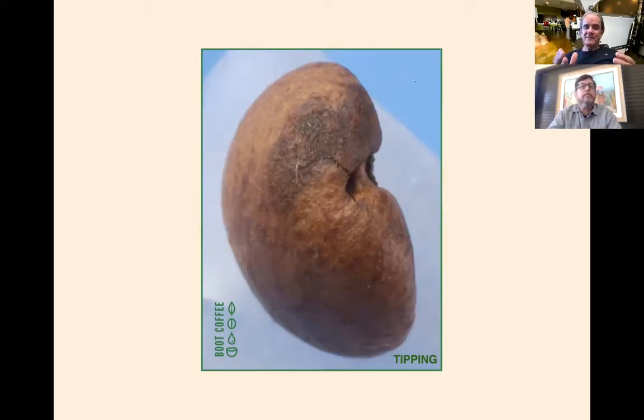Could be an issue with the roasting drum itself, but it could also be an issue where, if you're roasting with a Giesen, which has double wall drums, and you're turning up the RPMs of your drum too high, then you basically develop centrifugal forces, which allow the beans to be pushed more towards the drum itself, which can lead to tipping.